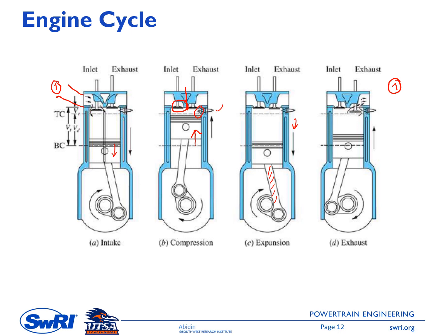The piston continues its way toward bottom center, and once it hits bottom center, the piston moves up again, and this is the exhaust stroke process. In this case the exhaust gas is displaced from this chamber going out through the exhaust valve, exhaust port, exhaust runner, and so on, exiting the engine by this piston movement.